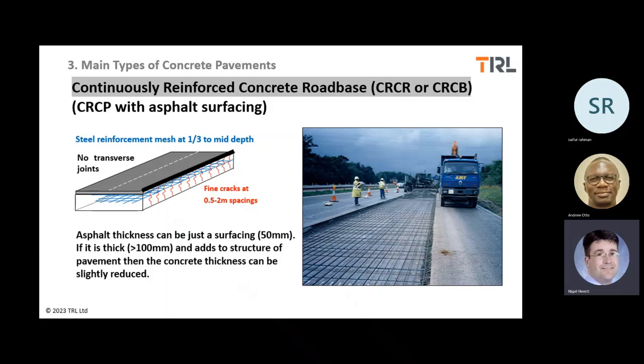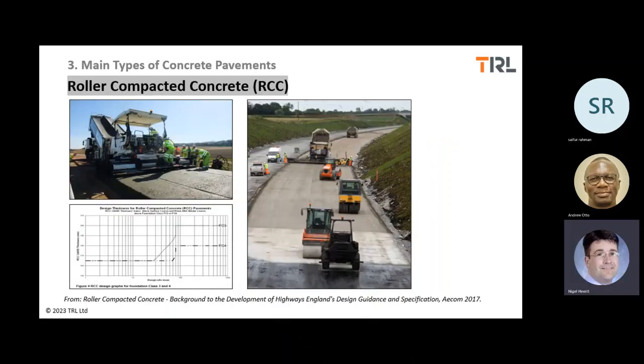Okay, so that's now roller compacted concrete. This is relatively new, and what happens is you're laying the mix. The mix is very stiff, so that as soon as you lay the mix, you can walk on it. So you don't necessarily need formwork at the edges. It's normally paver laid. So you pave it. I think you can use an asphalt paver. It's a very stiff mix, very low water content. As I say, as soon as you've paved it, you can walk on it.